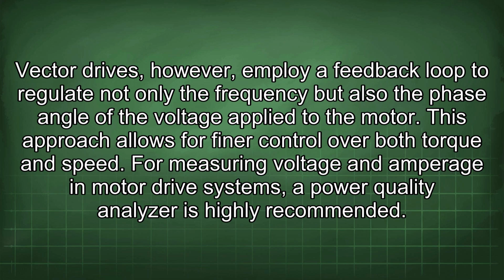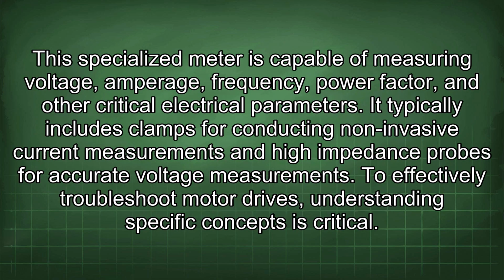For measuring voltage and amperage in motor drive systems, a power quality analyzer is highly recommended. This specialized meter is capable of measuring voltage, amperage, frequency, power factor, and other critical electrical parameters. It typically includes clamps for conducting non-invasive current measurements and high-impedance probes for accurate voltage measurements.